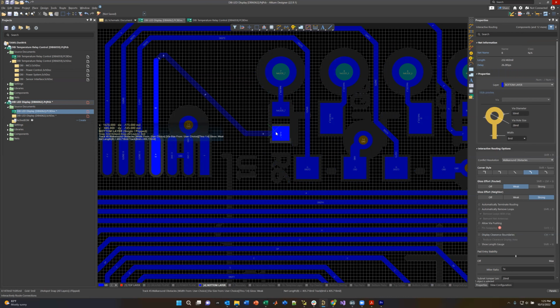Here's the connector for the display. I'll be showing that in a second. Here's those 4 switches. Here's the microcontroller. Pin 20 was power. I kind of remember that from earlier. There's power. There's the decoupling capacitors to provide a little bucket of charge. There's the crystal oscillator we were looking at earlier. And so on and so forth.